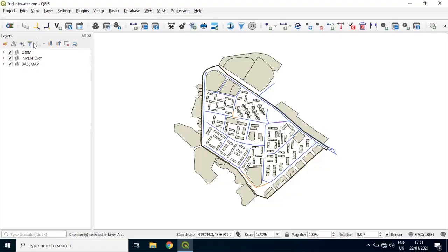With Giswater, it is possible to create a user operation and management for urban drainage. This user can perform analysis related to the work involved, from drawing sewer profiles, flow trace, flow exit, add visits, manage visits and select data by date.